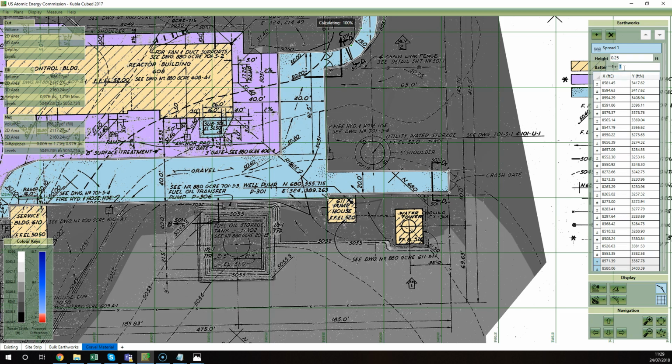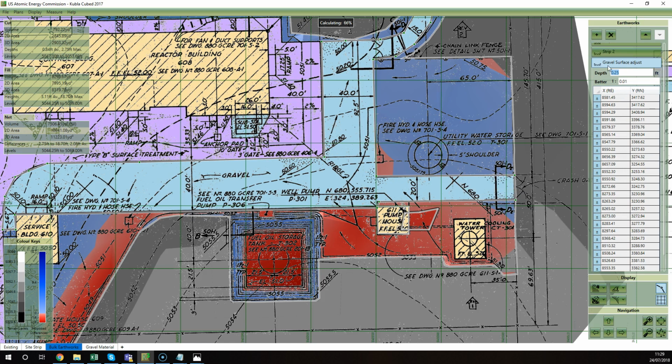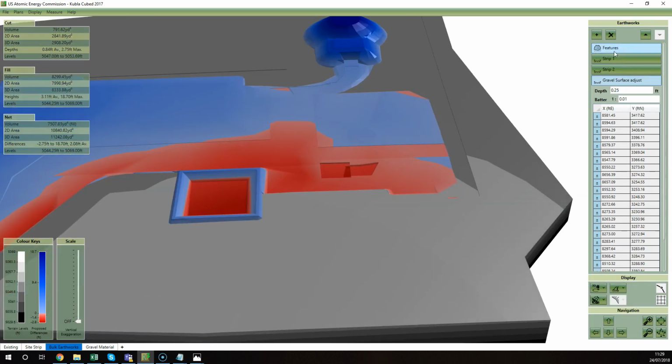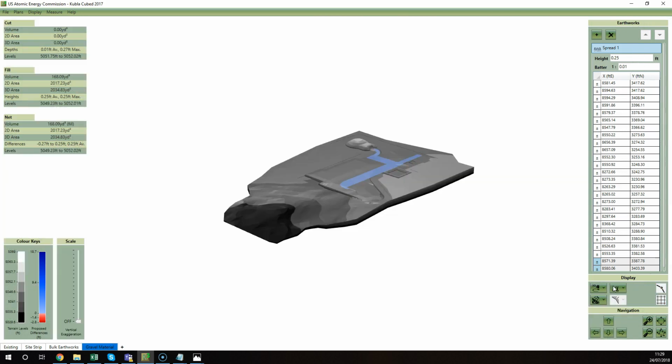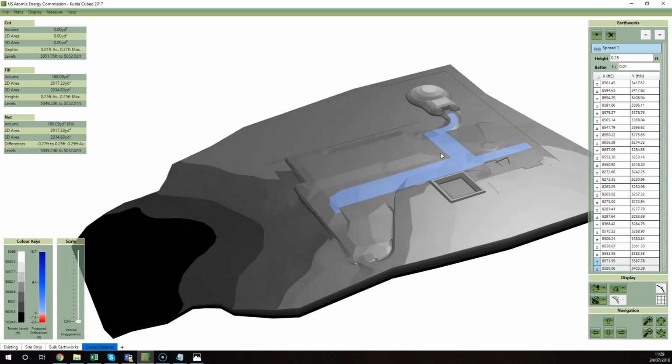And it's important to set the batters to 0.01. Just double check that I've done that on the bulk earthworks. I don't think I have here, so 0.01. To quickly explain what's happening here, this strip is adjusting for the gravel surface down 0.25. So in the report, we will actually have a cut and fill of the features with that section adjusted to the subgrade. Now in this phase, we have the spread over the same area with the height counteracting the depth that we specified with the strip. So it basically does the reverse. And that means in the report, we're going to have a fill volume for that material here.